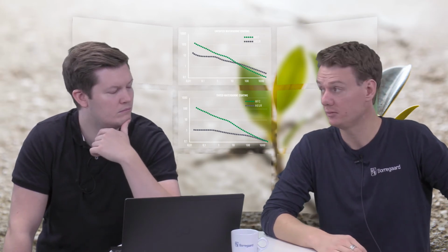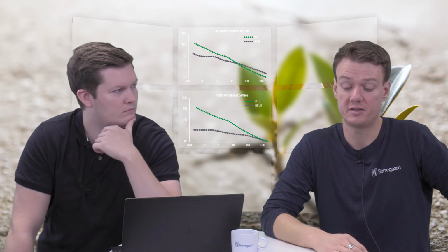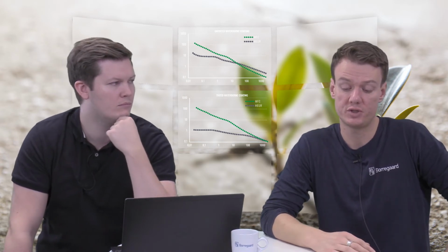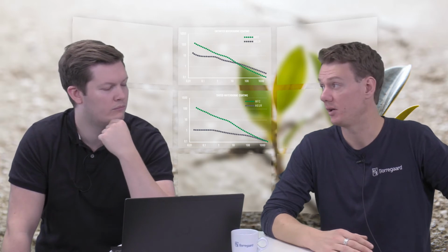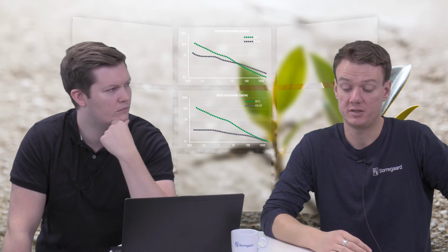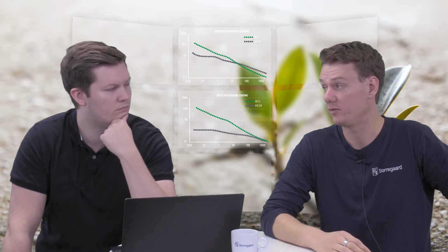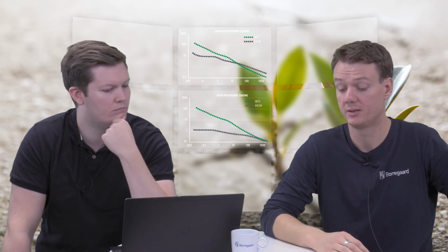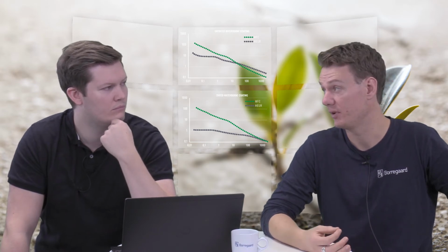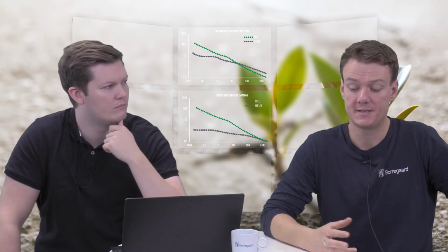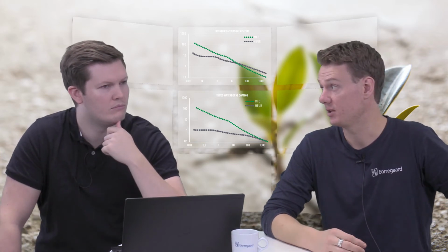But with Exilva, if you look at both the untinted and the tinted, the curves are pretty much identical. So at the low shear end, you get this much better viscosity rise compared to the associative thickener, and as you increase the shear, you have much superior shear thinning properties. And that improves the flow, and things like spraying can become a lot easier. And this is again repeated with the tinted coating.